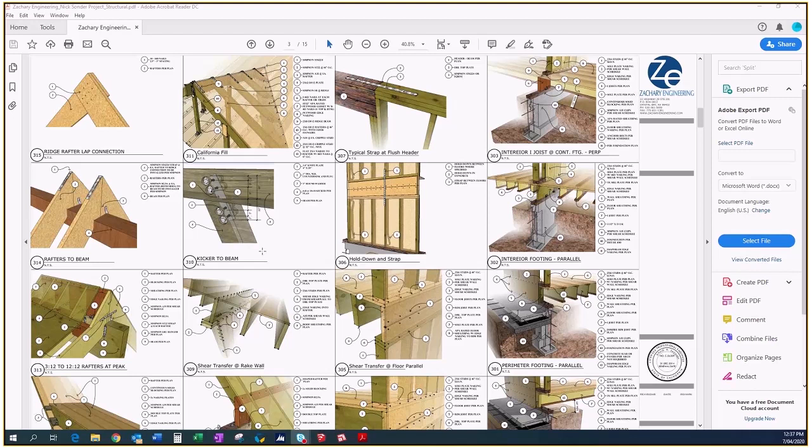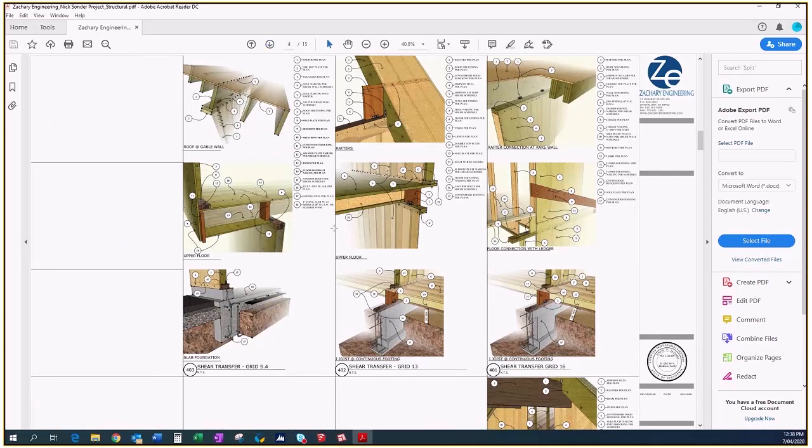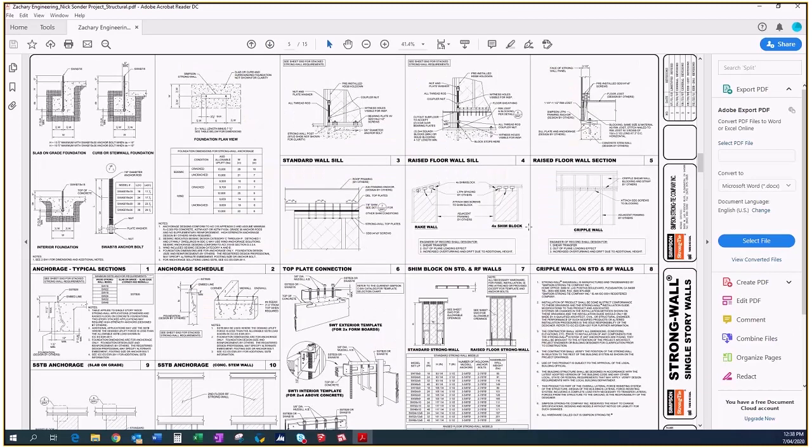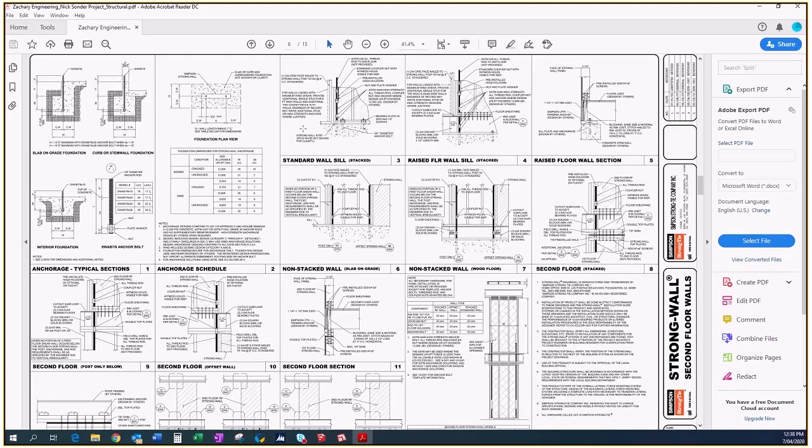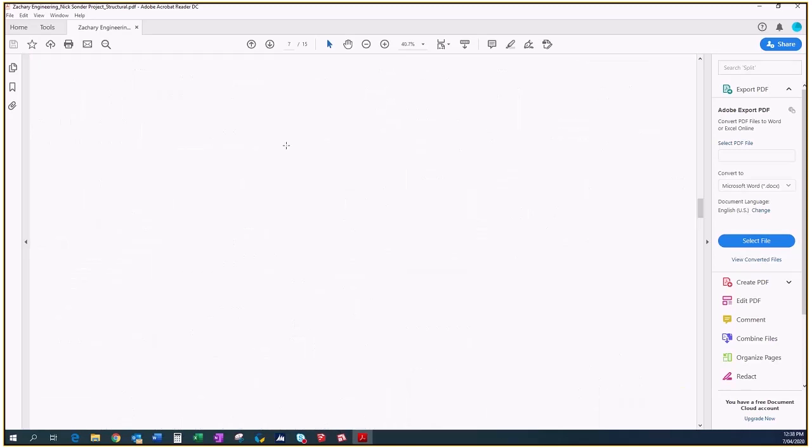In this particular case here, this customer has opted not to really do dimensions or callouts. Instead, they're using just this kind of bubble callout system, whatever you want to call it, or keynoting, I believe is the official term. So it depends on how you want to produce your details. But I think that gives a really nice overview and a combination. So 2D drawings inside the 3D drawing set, and I hope that most of you see the value between a 3D detail versus a 2D detail, but the 2D details will still have their place.